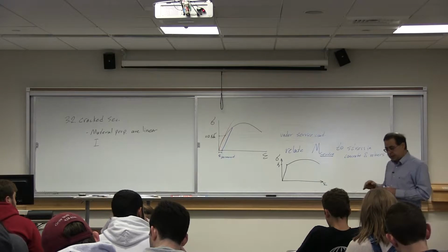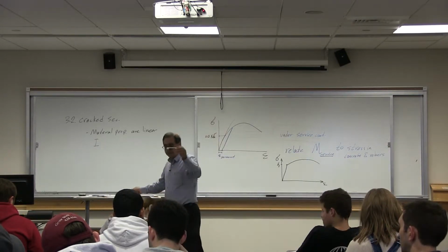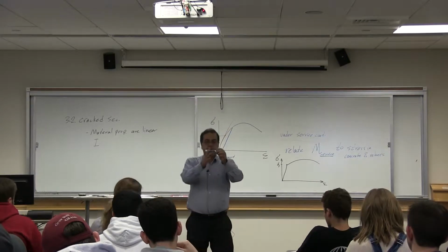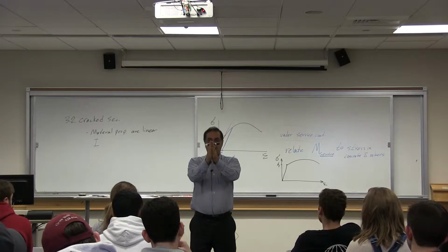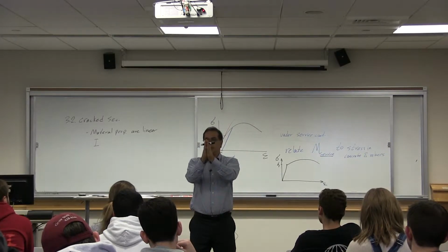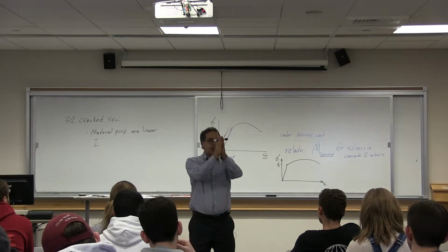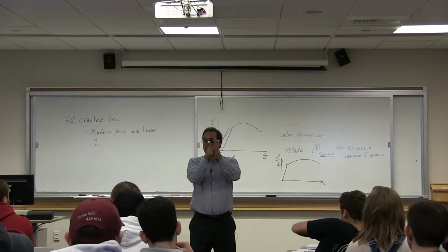You remember, we said you have a reinforced concrete section, and in this case I'm showing a negative moment. As long as the section is not cracked, the stress in rebars is not high. When the section is cracked, the only thing holding the two sides together is the rebar.